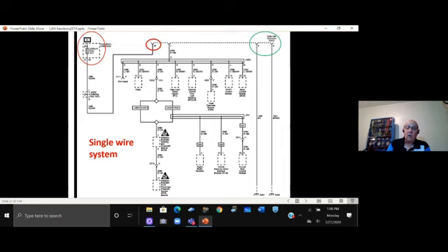And that ground goes to, in theory, 2 separate grounds. But I'll be honest with you, in some cases, they're banded together somewhere in the car and they wind up with 1 ground. It's been done all the time. You have to have power on pin 16 and ground on pins 4 and 5 for your scanner to work. If you plug a scanner in and you get no communication, get a multimeter out and make sure that you have power on pin 16 and then you have grounds on pins 4 and 5.